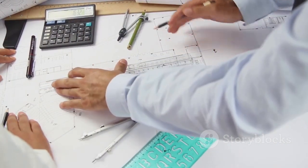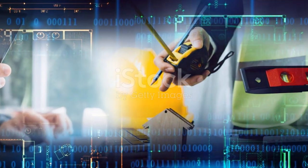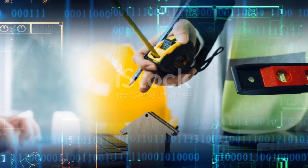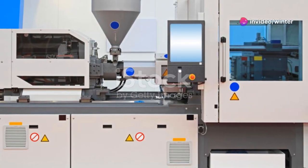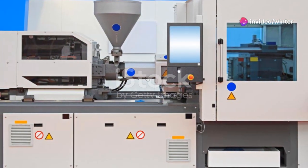Draft isn't optional, it's essential. Add it early, not after the mold is cut. Make draft angles a habit in every design. It's a small detail with a huge impact on cost and manufacturability. Don't skip it.